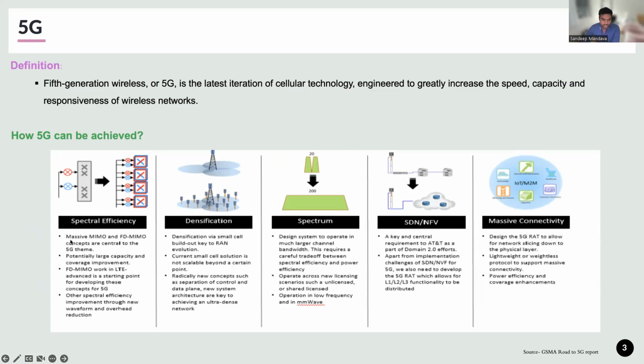And how is it doing it? There is a concept called massive MIMO. Earlier I mentioned 4x4, 8x8 MIMO, and massive MIMO is like a bunch of antennas. There is no precise definition to it. People call it 100 antennas at the base station. It could be much more antennas at the base station. But basically what it means is a massive number of MIMO antennas that will help you send communication to different mobile devices using the same frequency. And that was not there in LTE.